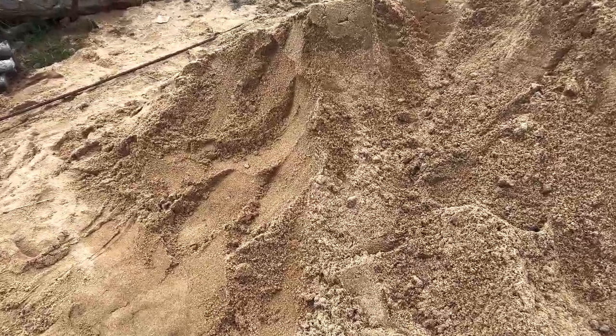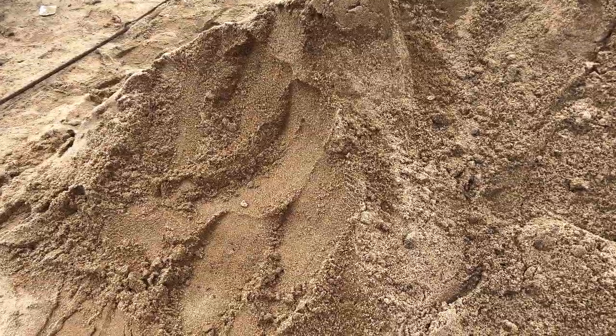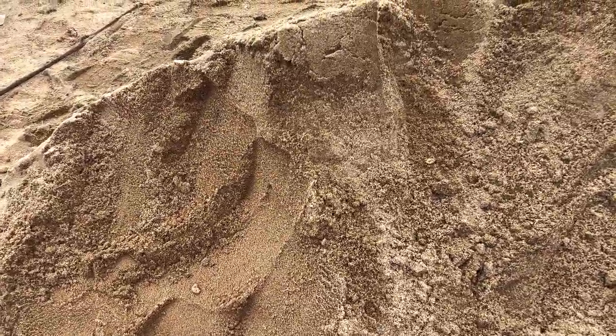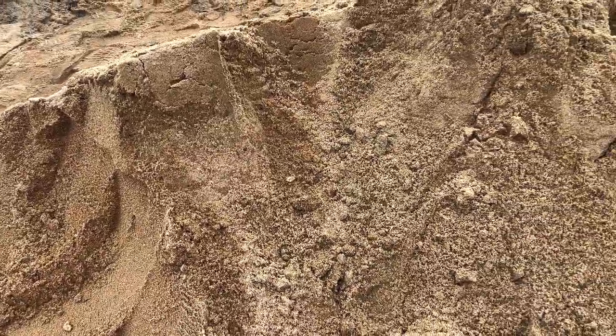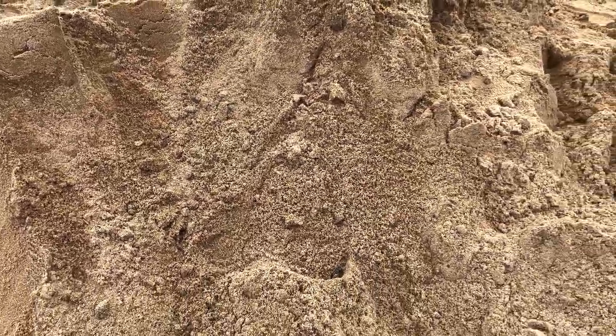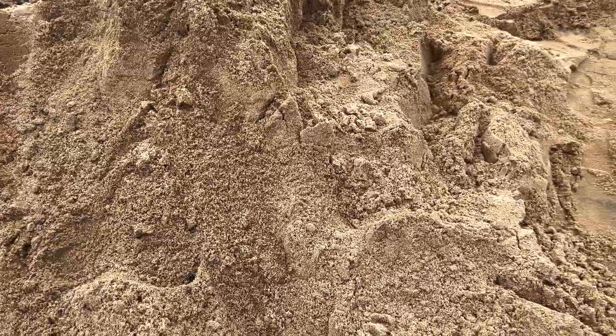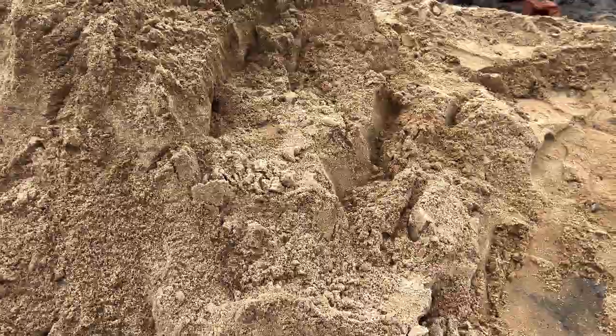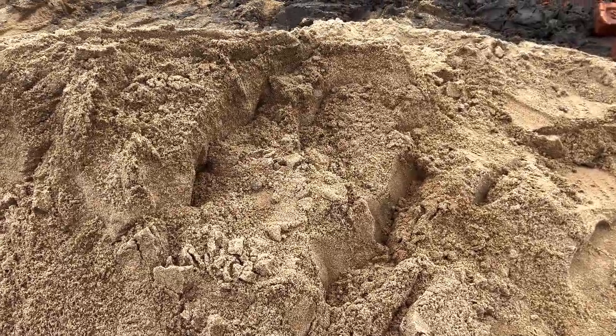Same for the fine aggregate. Suppose it is 800 kgs and if we take 800 kgs, there is some percentage of water in it. So, what is happening? The fine aggregate quantity will be less than 800 and the total quantity of water will be more than required. So, we are not getting our desired mix proportion, and if we do not correct the moisture as per the requirement, that will be harmful and a disaster for us. So, we need to calculate the moisture correction.